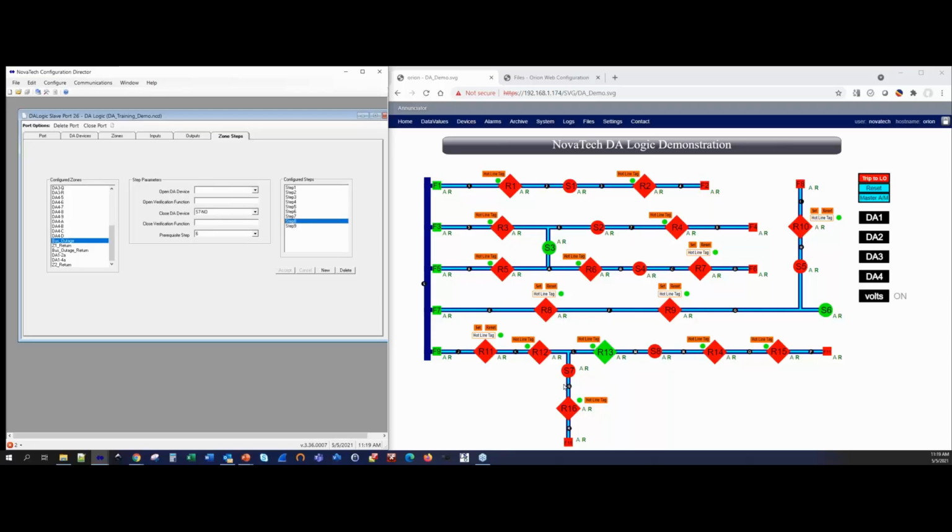And let's see, the last step that we had here was back for feeder F7. If switch 5 was not available, we still have the alternate switching at switch 6 to be able to restore here. So that becomes the more complex bus outage that can be done in DA.